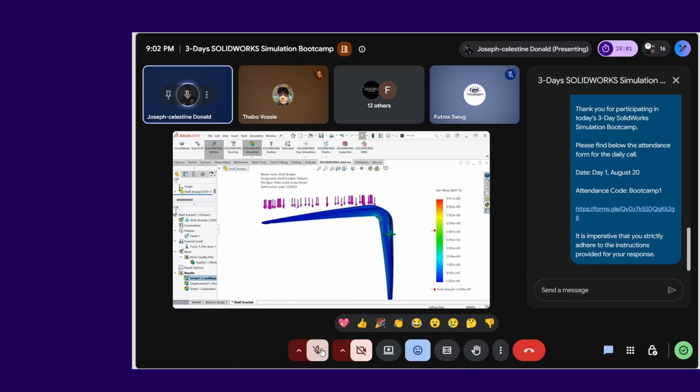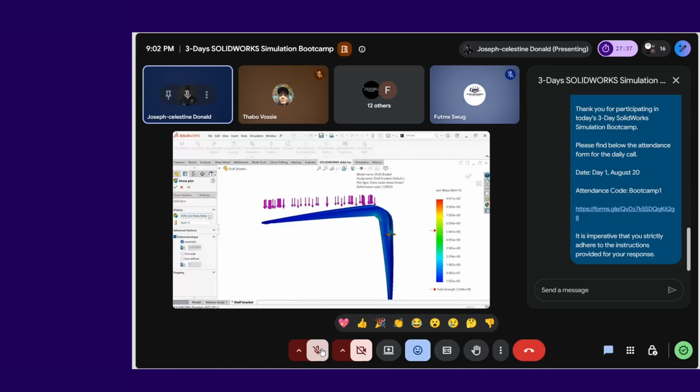All right. So now, the first thing you have to do is clean up your design. As it is like this, it's not showing clearly. First thing you want to do is right click on your stress, edit definition. For mean stress, you want to turn this to megapascal first.